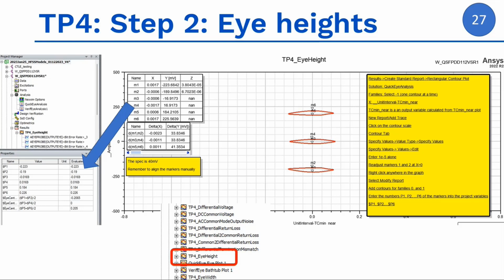The standards allow us to do some equalization. I just assume no equalization, whether on the TX side or the RX side, on the host side or the transceiver side. That's why I am violating the spec, because I made my transmission lines intentionally very bad.